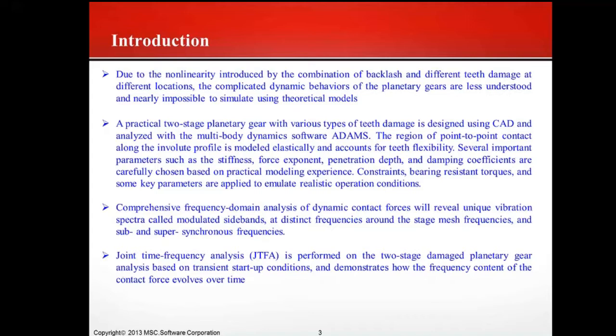Maybe the majority of engineers or researchers will think Adams focuses on rigid bodies. But actually, in our case, we model the majority of the parts as rigid bodies, but the teeth we make as an elastic body by carefully choosing the parameters.